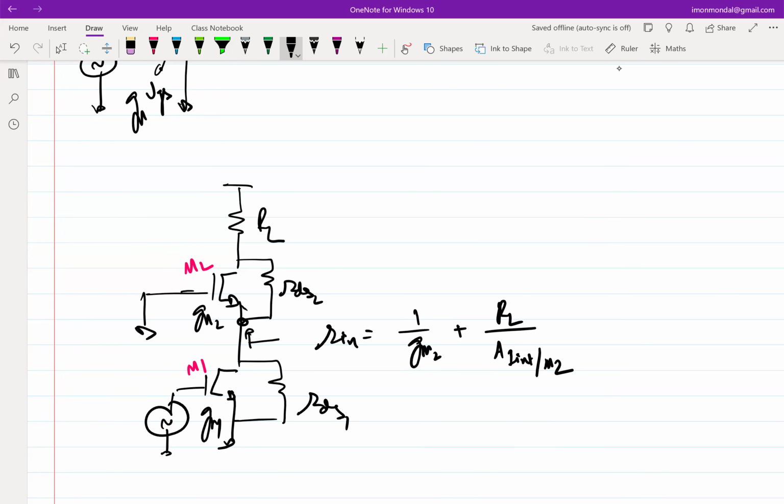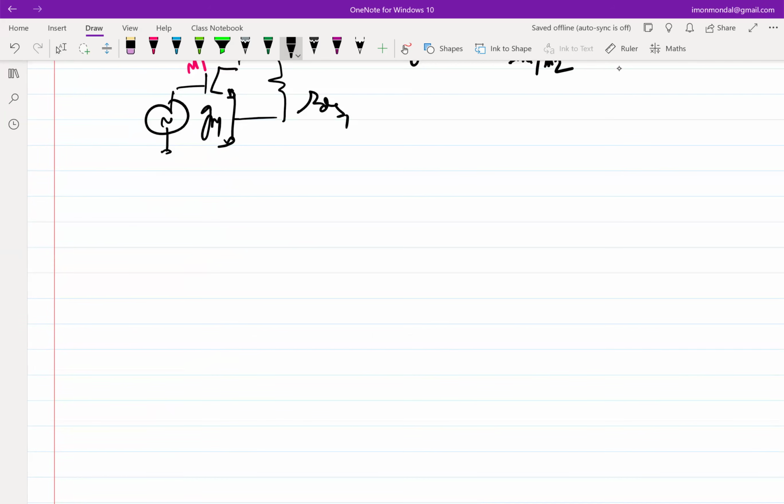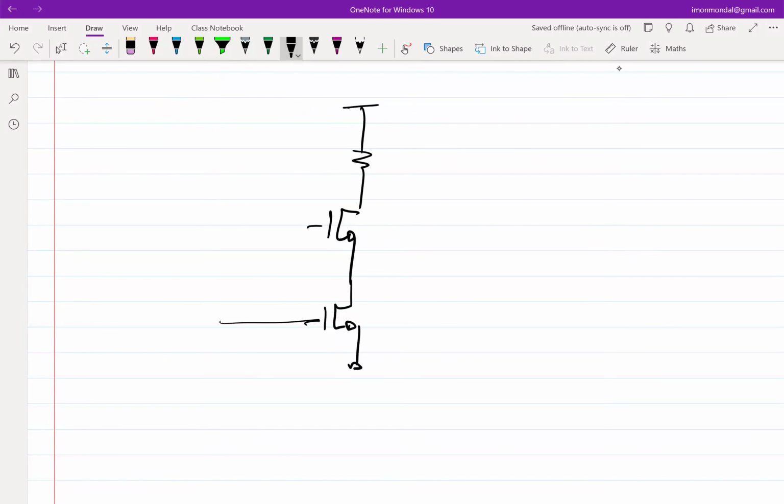Okay. And then we also were trying to bias this circuit, and we have done this biasing in a different context multiple times. So this requires a VGS, and one way to bias is to put a battery or a voltage divider, a resistive divider, to generate the exact VGS. But we now know enough to understand that that type of biasing is probably not very accurate with regards to change of threshold voltage, change of mobility, and so on. So we would like to bias it with a constant current source. This is one of the ways of biasing.